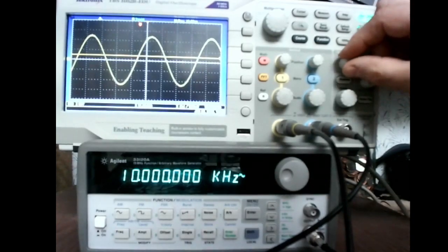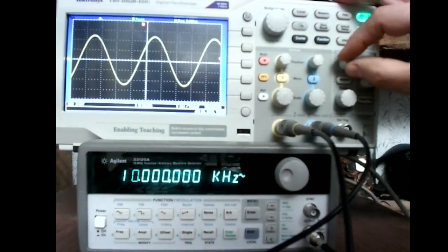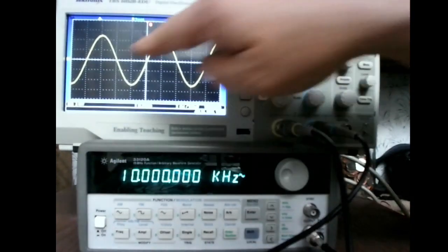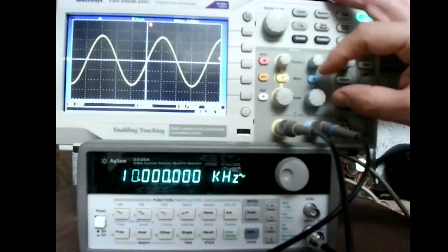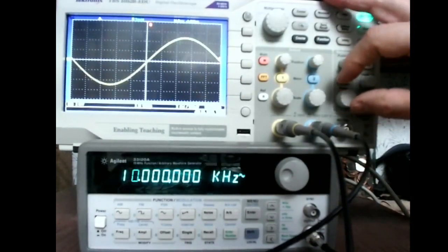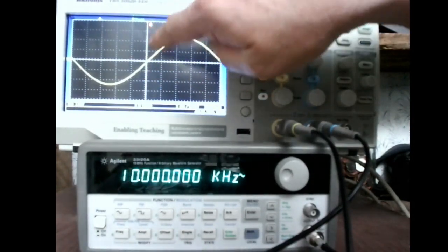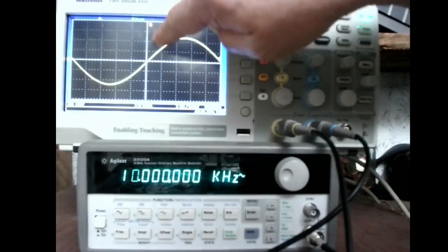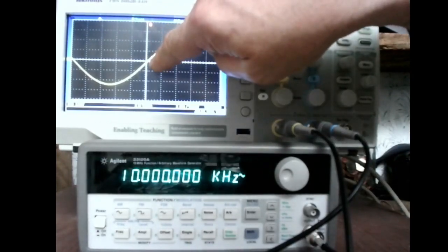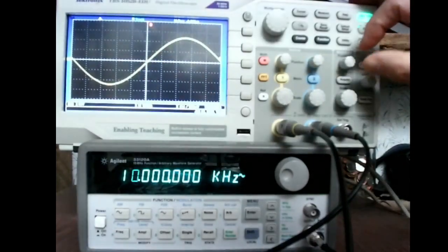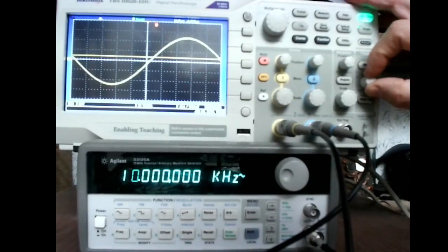As I mentioned in class, you can actually adjust the position of the sine wave so that it crosses at a certain point. Okay. So now this trigger knob is triggering in the center. You see up here it says T, that's the trigger point, and it's triggering when the sine wave goes up.